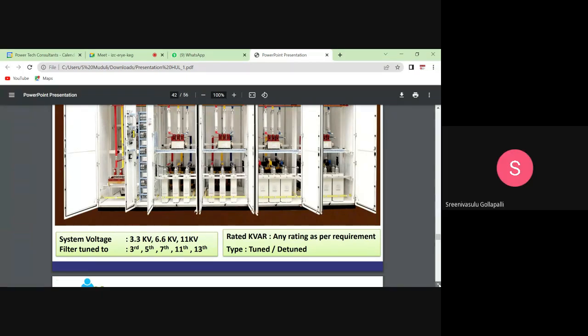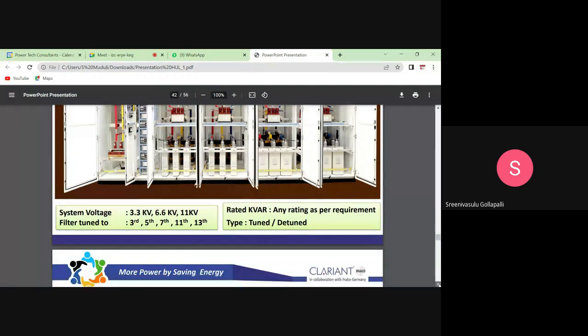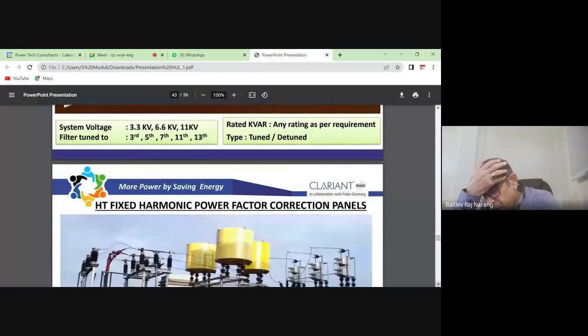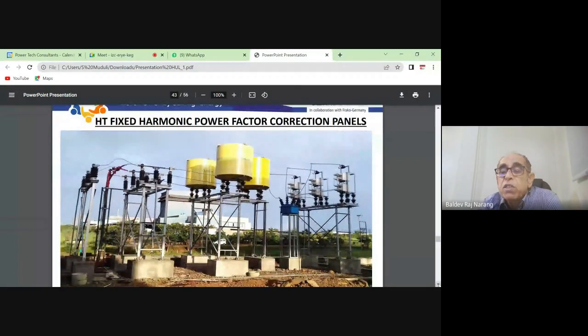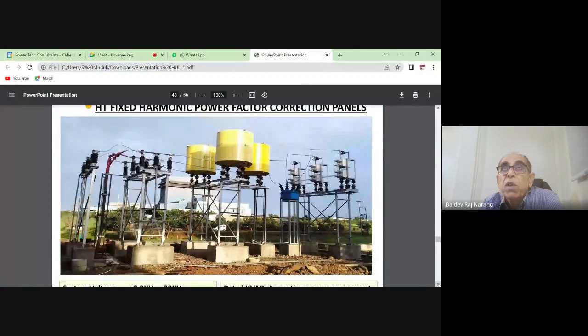Okay, sir. Is it the same procedure for welding loads also? Welding load is also the same thing. That also has harmonics. There, even the power factor is 0.4 or 0.5, particularly in spot welding and so on. There we have to design unbalanced compensation, for 3 phases. And the harmonics we have to handle the same way with the reactors, or even an active filter if the reactors are not sufficient. Then we have to put in active also.